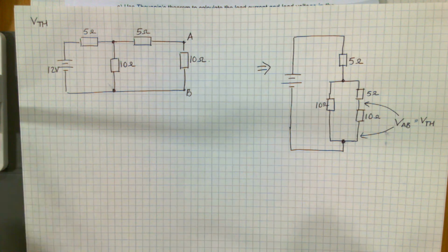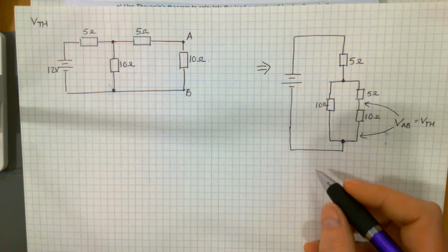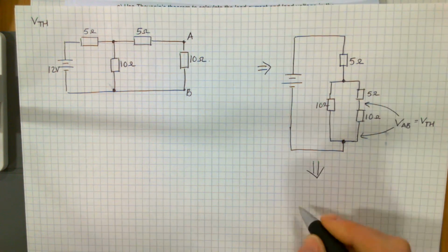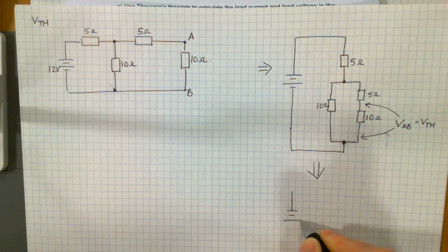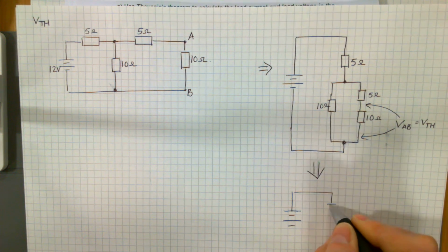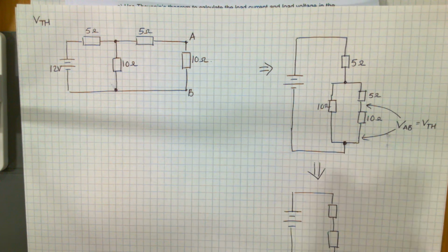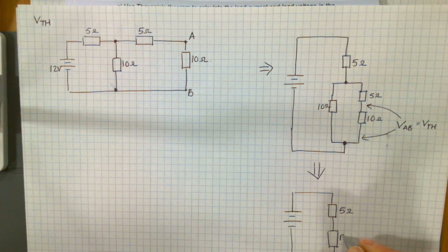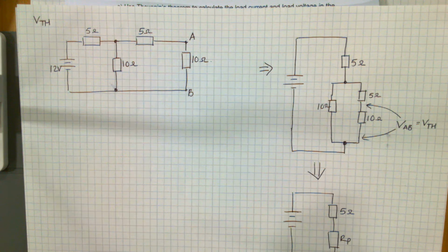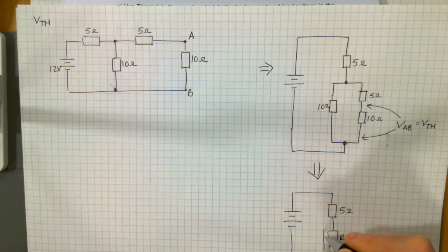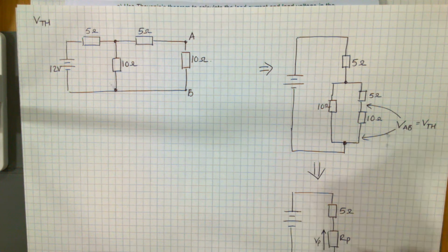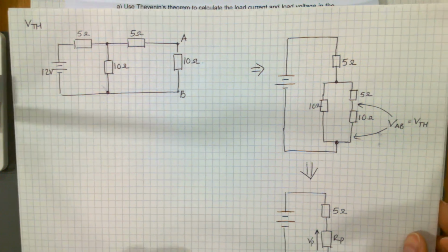From this, if you're wanting to work out the voltage across that Thevenin part, what you'd probably do first is work out the voltage across the parallel part and then divide that again. So you wouldn't use this circuit necessarily. You'd probably start off using a circuit like that. So you start off doing that, and you'd work out what your value for VP would be. So your RP first and then VP.